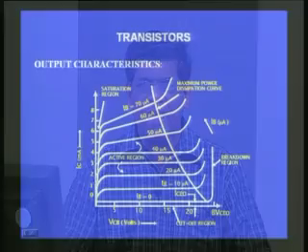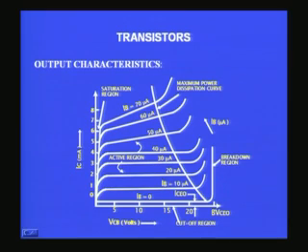So, VCE times IC is equal to a constant. Well, if IC is very small, the VCE can be very large. As we change the IC, you would find the maximum value of VCE keeps decreasing. So, it comes out something like a rectangular hyperbola, and therefore, I should never make my transistor work anywhere in this region which is beyond this curve, which corresponds to the maximum power dissipation curve.